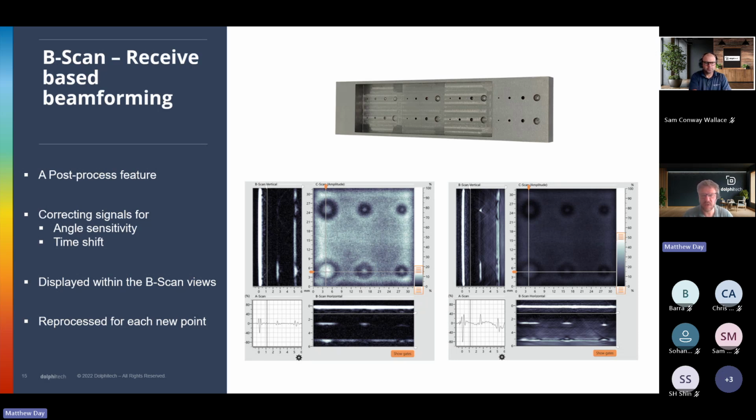So whether you're looking at, on this image here, the crosshairs are fixed on a flat bottom hole, but at the top you can see the difference between a rounded hole. So on the left, you just about see the deformation of the ultrasound, but on the right hand side, it can actually zero in and focus in on that tip of that sphere, a spherical hole.